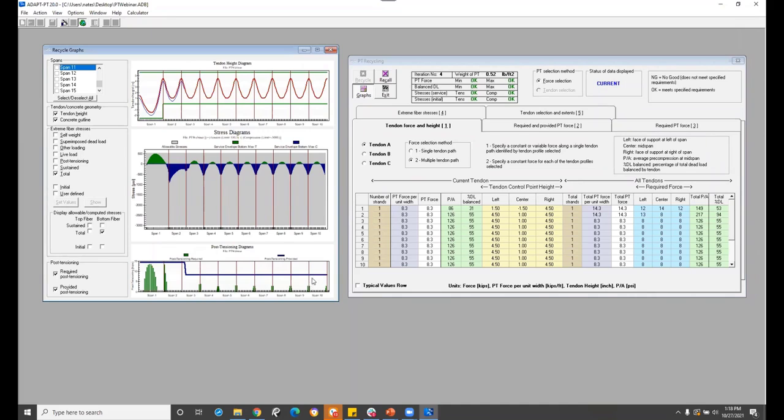And what I can infer from these graphs is that these interior spans could be wider if I really wanted to. And ultimately what's controlling this is the pre-compression, right? We have all this extra wiggle room, but if we lower the amount of tendons, we're not going to meet that minimum 125 pre-compression that we need. So I like this design. Let's go ahead and click exit.